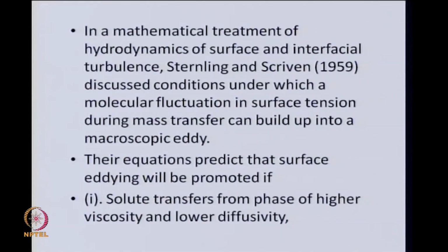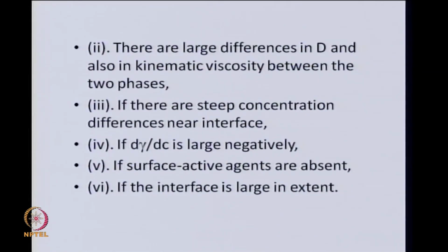So, eddying is possible in a system like ether water in contact with air, and transfer of ether is taking place from the solution into air. Second, if there are large differences in diffusivities and kinematic viscosities between the phases. Once again, a valid case, the liquid against the gaseous phase. We expect the diffusivities to be very different and the kinematic viscosities also, because one is a dense condensed phase, another is a rare gaseous phase.